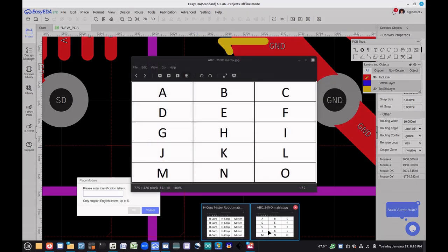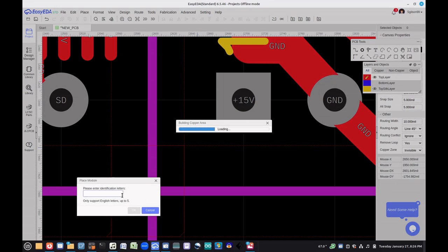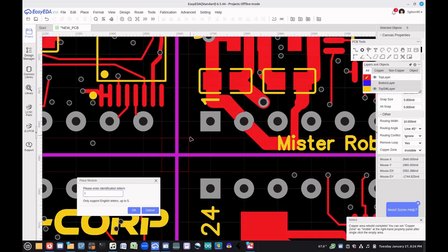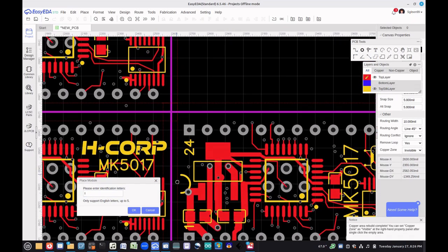Next one is going to be I. One of the things that happens with this, because of the fill that I do on the layers, is all the boards short together on the different layers. So even though the nets are unique with their letter prefix, you'll get DRC violations. So you don't run a DRC at the end because you've already run DRC on the individual ones.